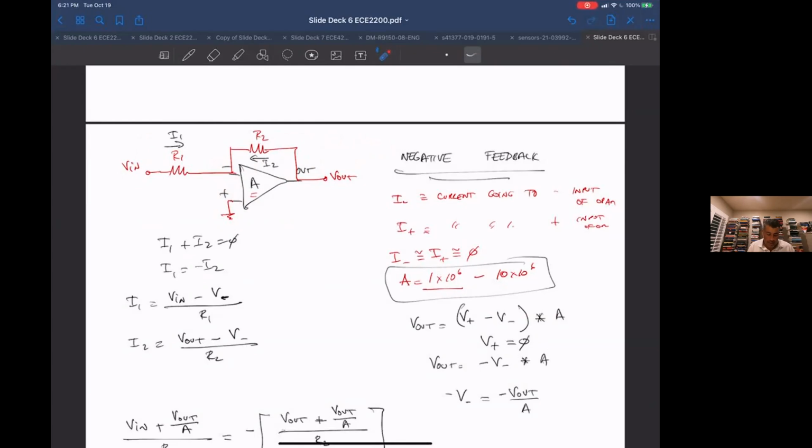But the nice thing is that, as we'll see, a lot of what we're going to use is the concept of small signal models. This important thing about small signal analysis, we saw it in the diode, if you remember. We're assuming that the voltage changes are very, very small. That's how we can use these small signal models to make our designs easier.